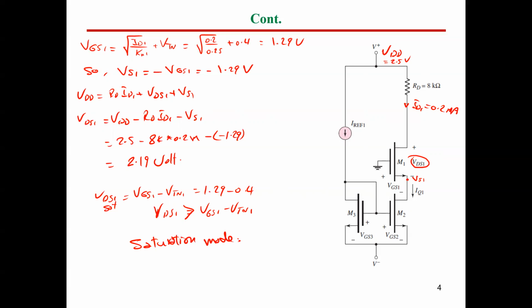From this circuit, guys, we found that we can control a current in another transistor by connecting two MOSFETs with a common source, with the gate connected to the drain of M1, and the reference current coming from here. This can be used for controlling any kind of current in any MOSFET. So this is called a constant current source using MOSFETs. This is the first objective of our class today. Nice.